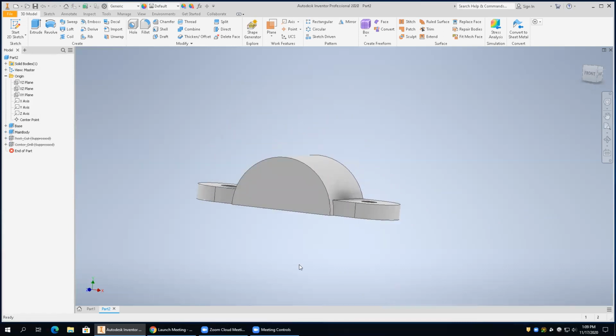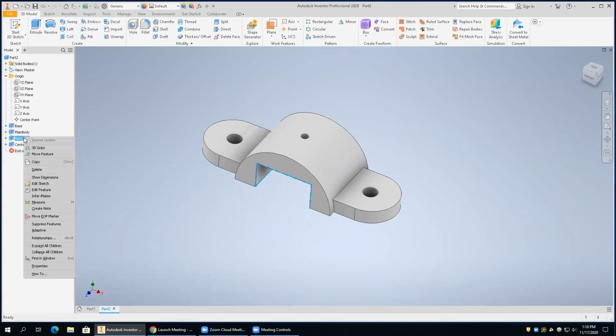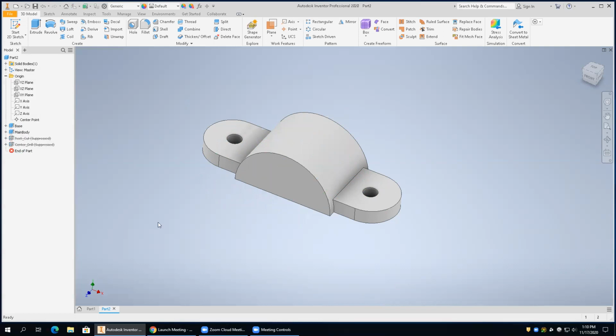The cut's no longer there, but also the drill hole's no longer there because the drill hole was linked to that, right? Notice it automatically suppressed the drill hole, but you couldn't unsuppress it on its own. If I unsuppress that, it unsuppresses everything, because they're linked. So you can't unsuppress the one if it's linked to the parent.